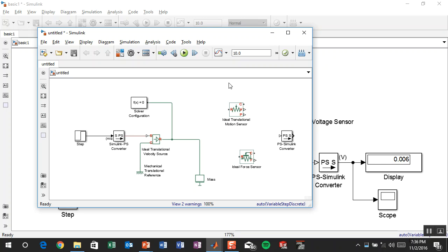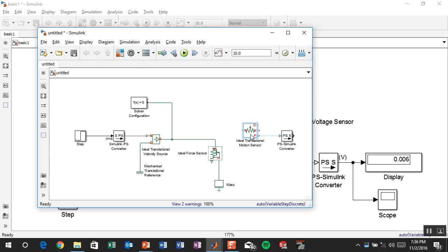You have to put it in series. And voltage is, of course, the across variable you can do in parallel, and that's why we hardly ever measure current, because you have to mess with the circuit. Well, in the mechanical domain, force is the through variable, so we have to connect it in series. And velocity is the across variable.